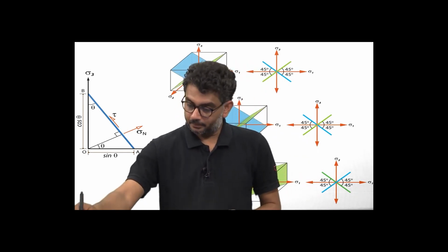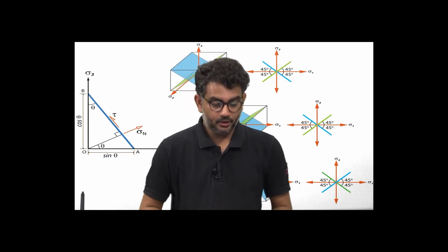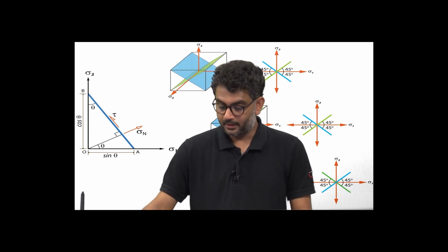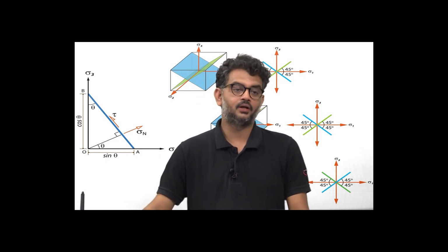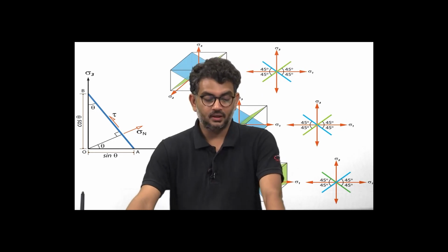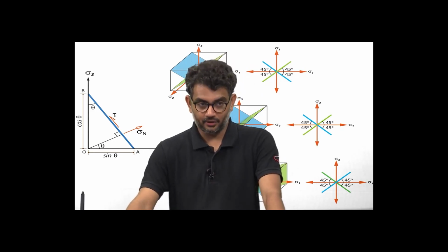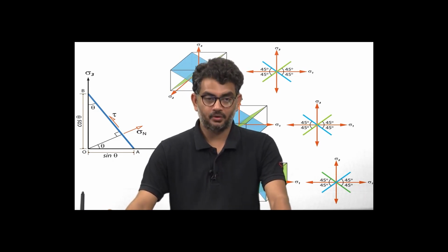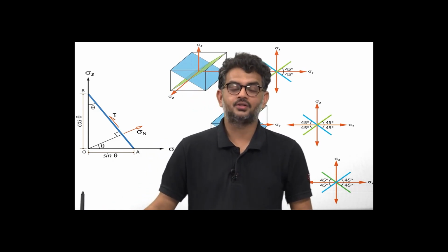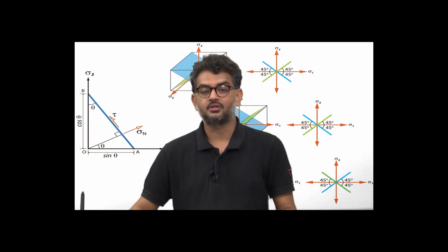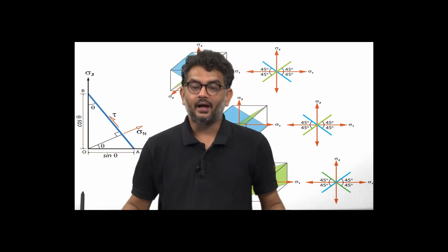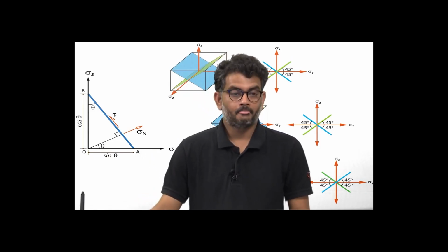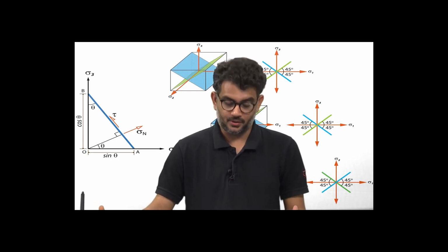So, let us go to another very important topic of the stress subject that we always consider, particularly in structural geology, which is isotropic and deviatoric stress. You can actually decompose a general stress tensor into the isotropic, sometimes called hydrostatic, and deviatoric stress matrices or stress tensors. Now, what is isotropic state of stress?